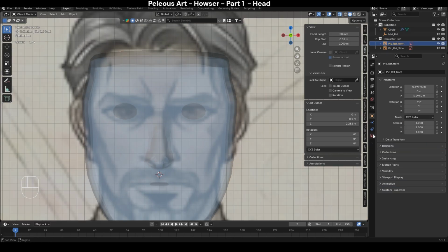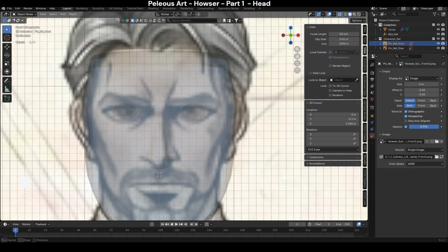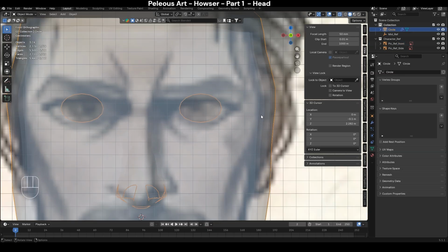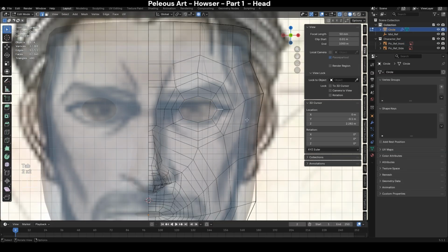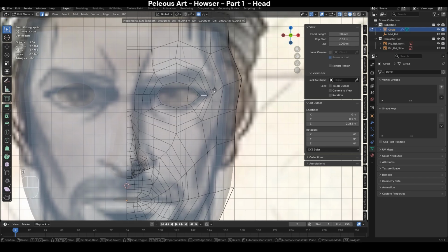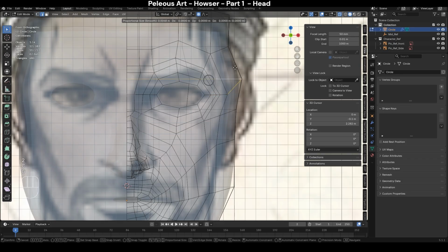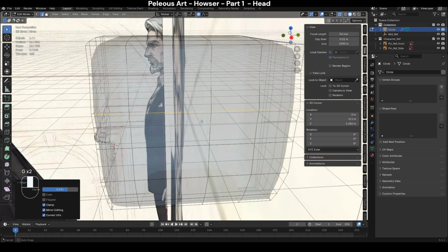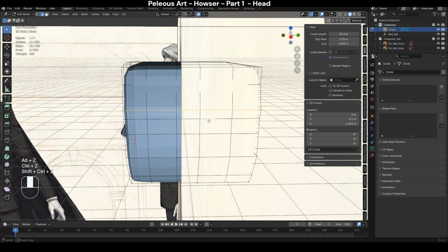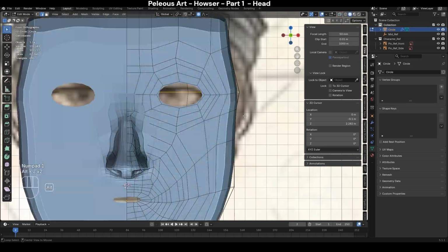Let's fix the opacity a little bit so we can see the picture. Make it 1. Just for now, you can bring it back in a moment. Let's move it to the side a bit to match with a reference. So just this edge, and with proportional editing, we're moving. Pull it down. Not this one. There we go. GG to slide. Okay, without the one that's close to the eye. So this way we pulled the whole row, the whole edge down.